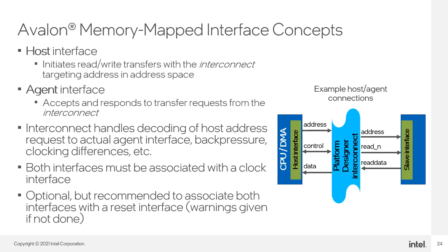Both host and agent interfaces must be associated with a clock interface, since all memory-mapped transactions must be synchronous. While not required, it is recommended that all host and agent interfaces are also associated with a reset interface. Warnings will be displayed in Platform Designer if there is no reset interface association, but the system design can still be generated and function.